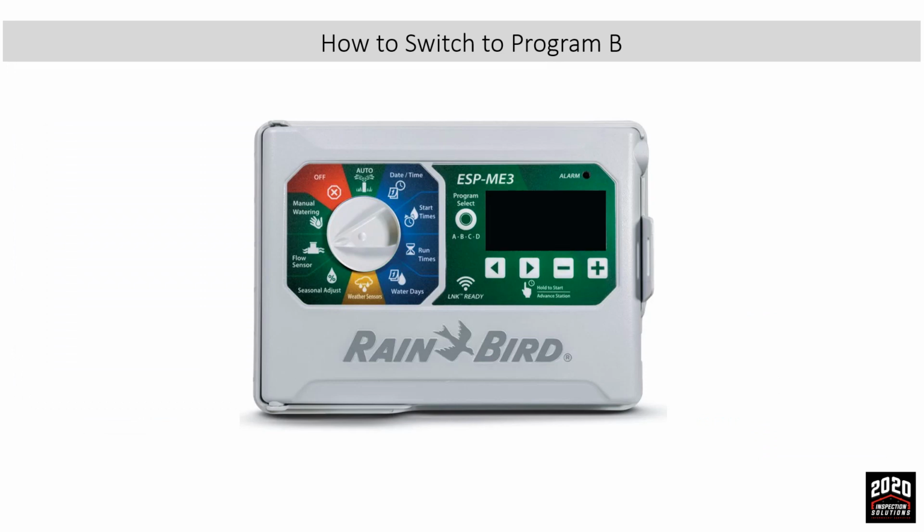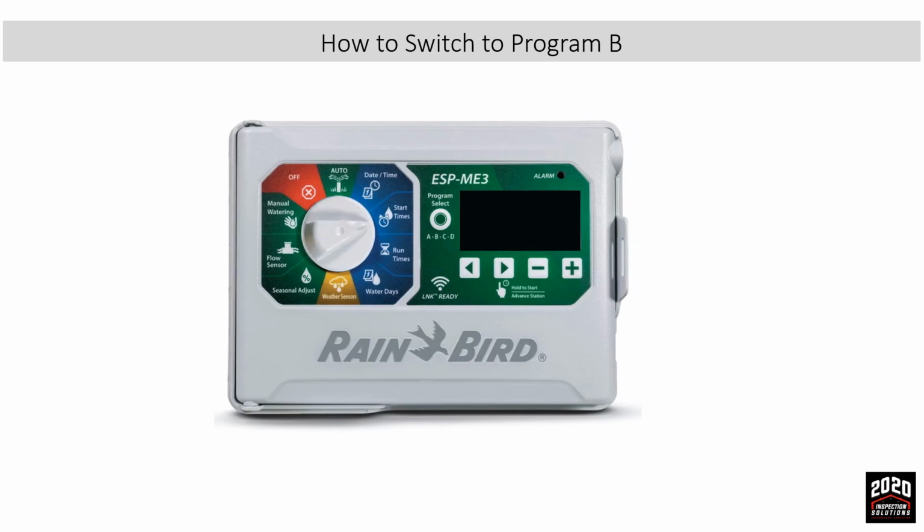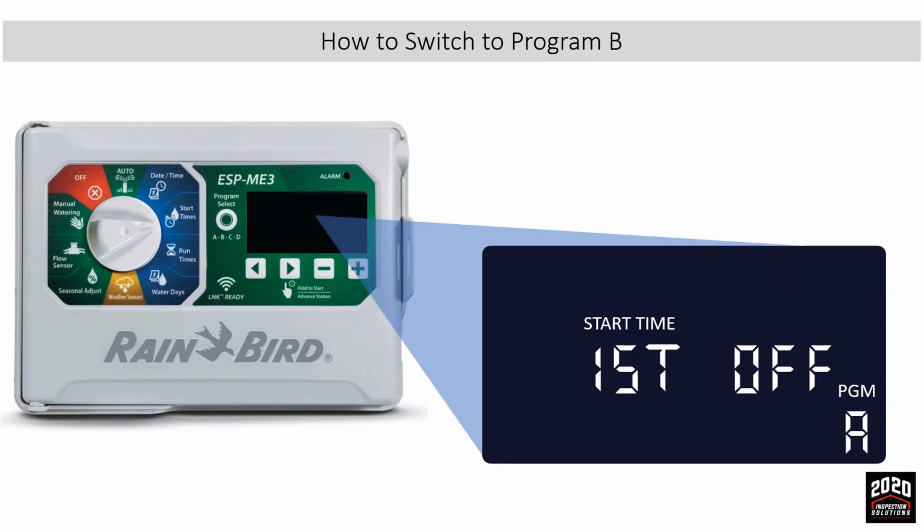Switching to program B. To switch to program B you can be in start times, run times, or days to water. But we will turn the dial to start times. Then press the program button to go to program B. Then repeat any steps if needed or wanted.